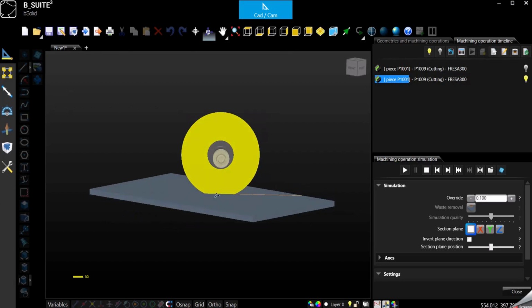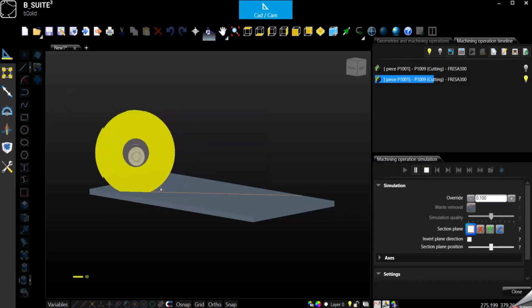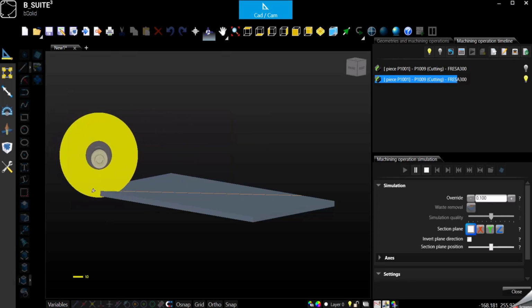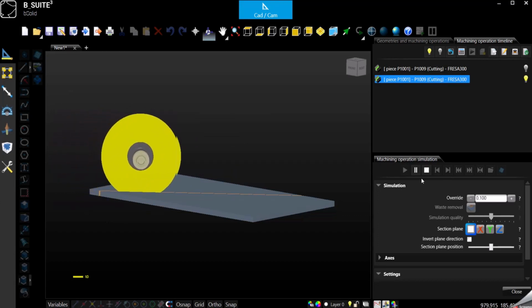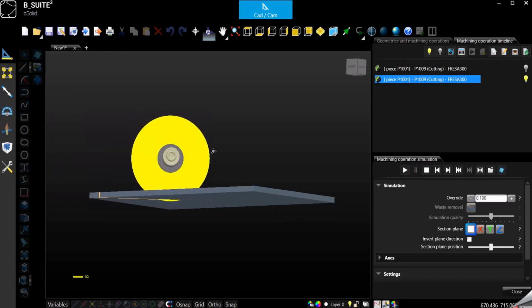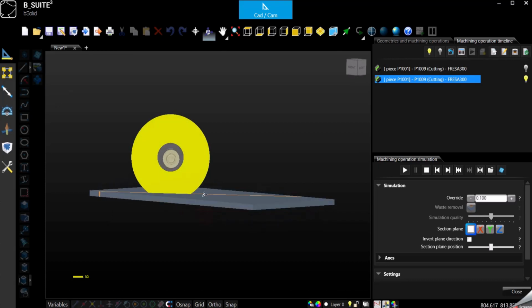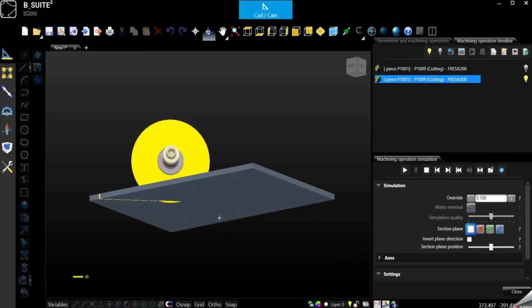And since I'm not all the way through, when the blade gets to the end, it goes down and comes back. In this case, consider that I'm still spinning in the same direction, counterclockwise. In this case, my teeth will push up my melamine. Of course, the top is already cut, so it will not chip, and the bottom will not chip either.